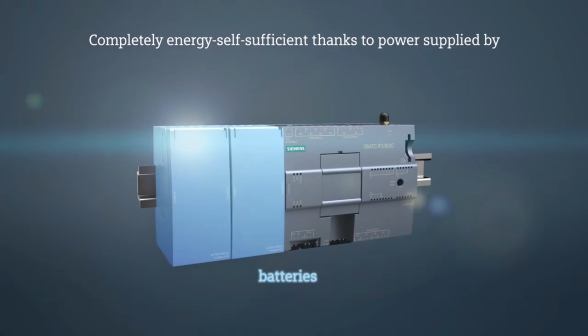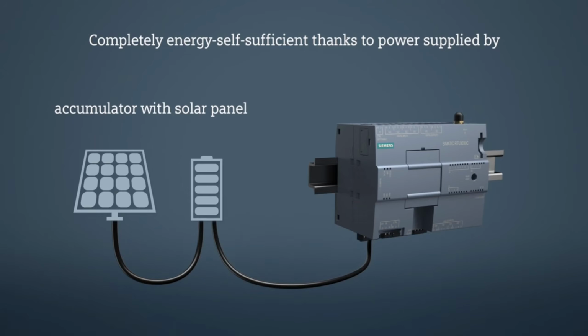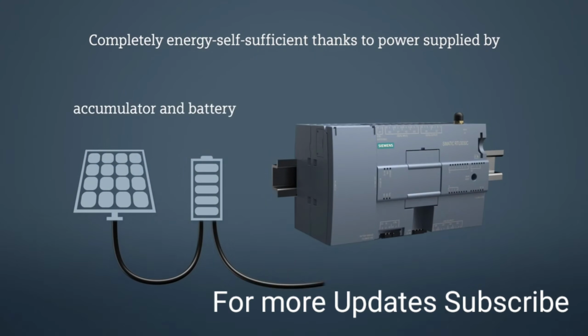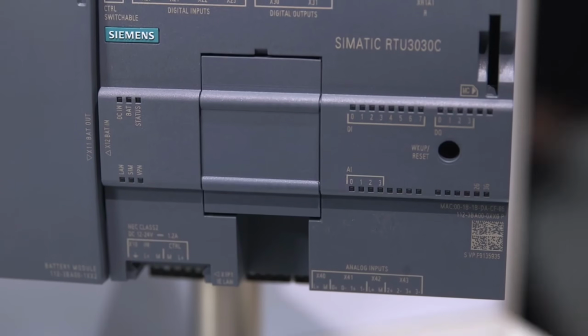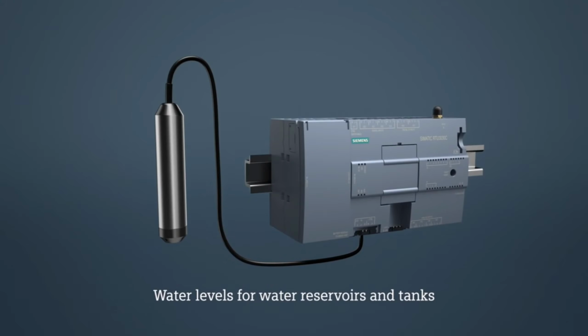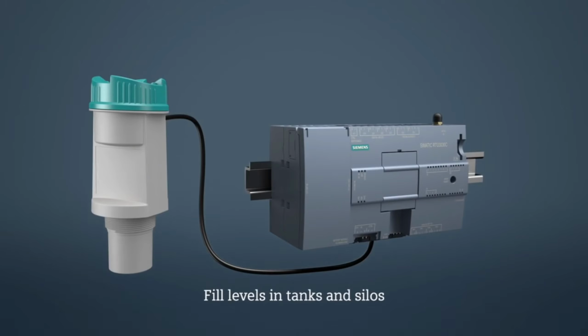It is energy self-sufficient by using a battery, an accumulator with solar panel, or a combination of both. The RTU offers 8 digital and 4 analog inputs, as well as 4 digital switch outputs. Different sensors for measuring the pressure, flow rate, water level, filling levels, temperature, etc. can be connected to the analog inputs, and the RTU serves as a power supply for the measurement.